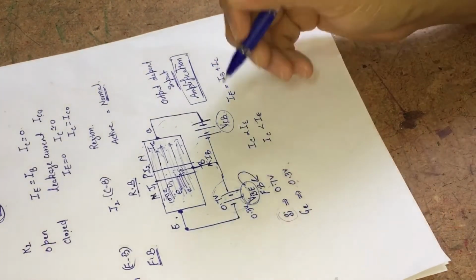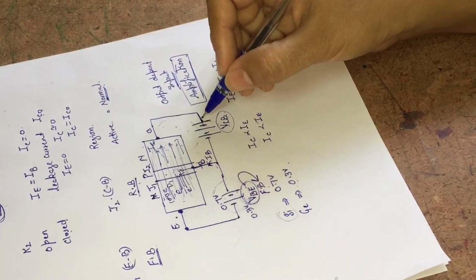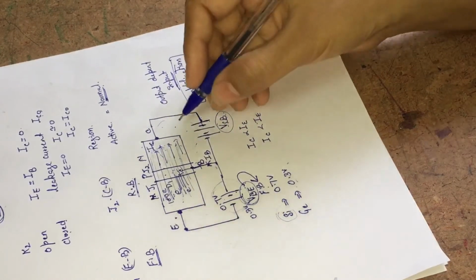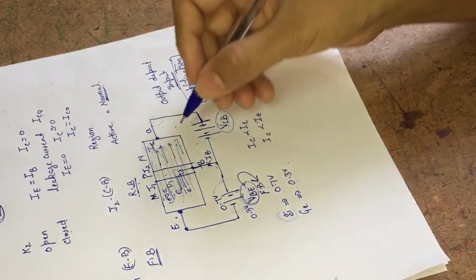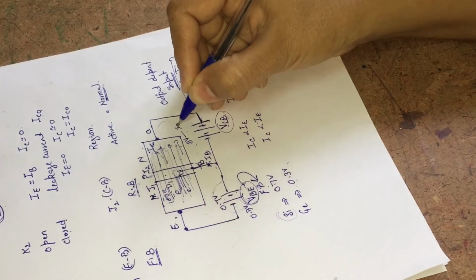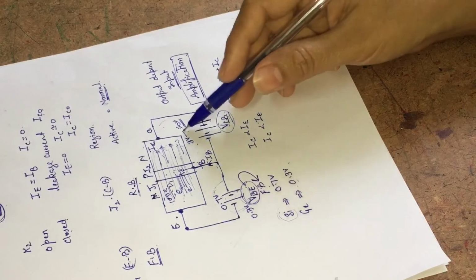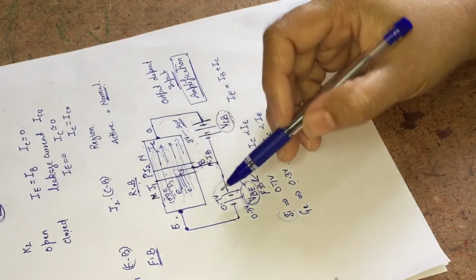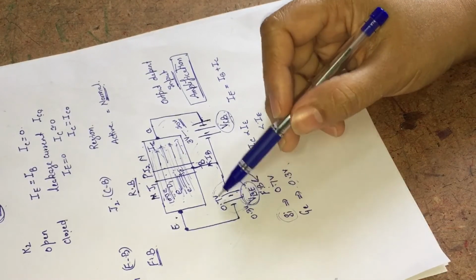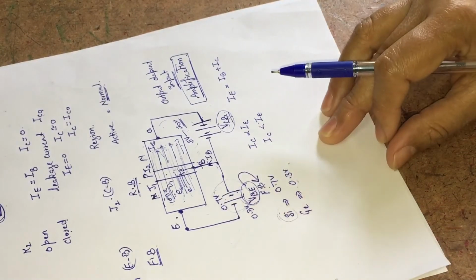On the other side, we have reverse biasing. In the case of reverse biasing, we know that we have to work the diode before the breakdown, and before the breakdown, the voltage in reverse biasing may be between 3 volt to 20 volt. It means in reverse biasing we have to apply this range of voltage, and in forward biasing we have to apply approximately 0.7 volt in case of silicon and 0.3 volt in case of germanium.